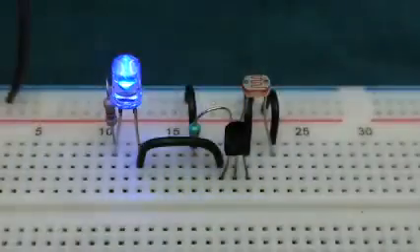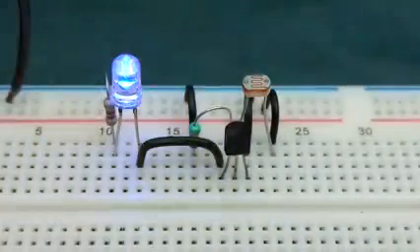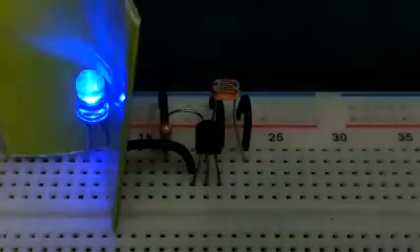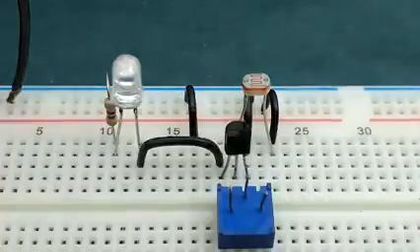The sensitivity of this light sensor depends on the series resistance to the LDR. At 1 kilo ohm, the sensitivity is low. That is, the LED turns on only above medium level of brightness. If you replace it with 10 kilo ohms, it turns on LED even if there is little light. So if you wish to have adjustable sensitivity, you can replace the series resistance with any two adjacent leads of a 10 kilo ohm potentiometer.